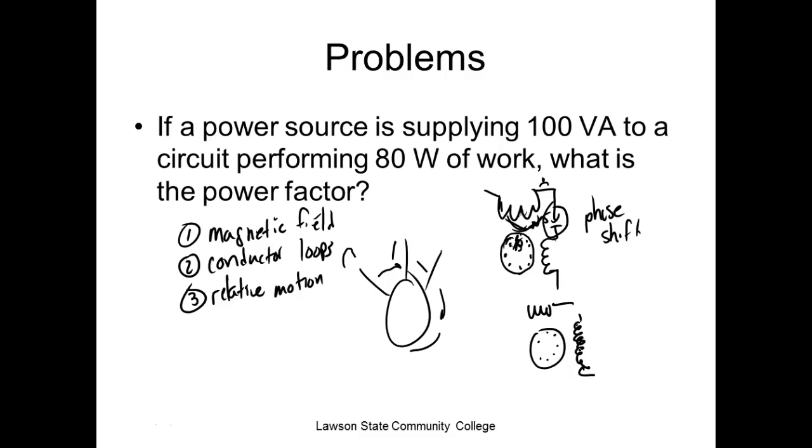We call them overloads. That would sense if you lose one of your phases and the current in the other two phases tries to go up, because that burns your motor. Burning the coils up on a motor is a very, very expensive proposition. I mean, rewinding motors is not cheap because it's not easy to do. We got some videos we'll show y'all where they show them actually making motors and how they wind up stuff.